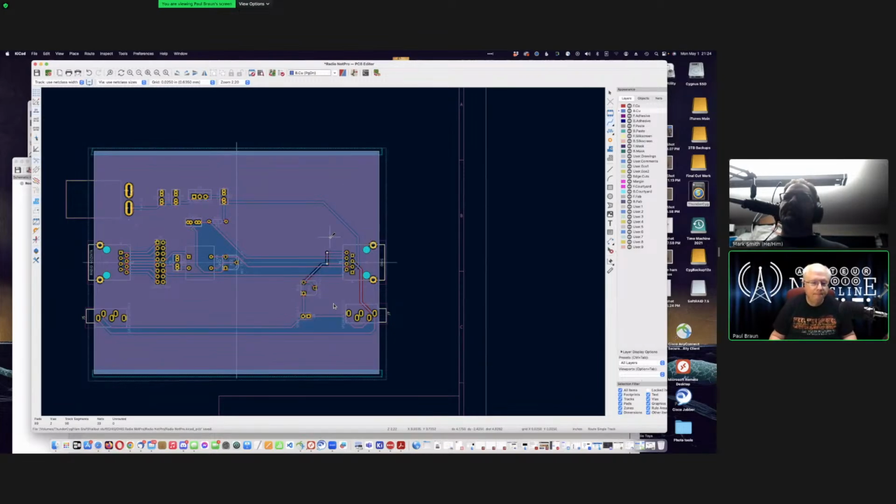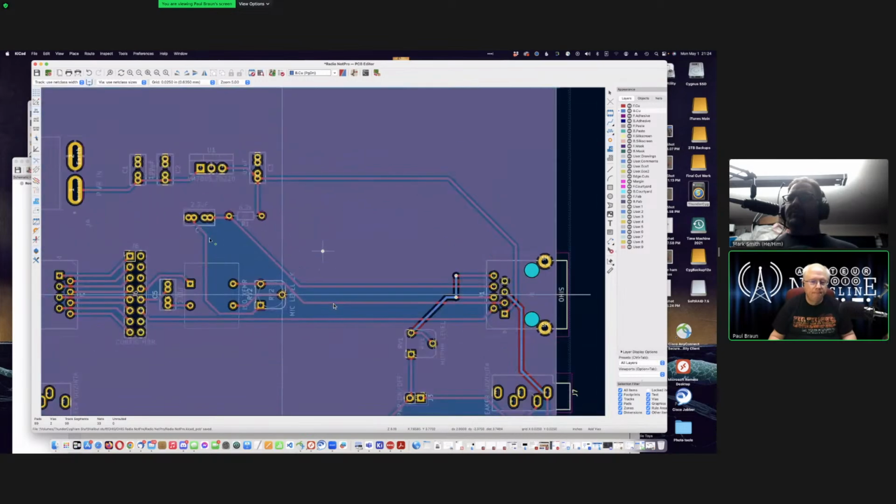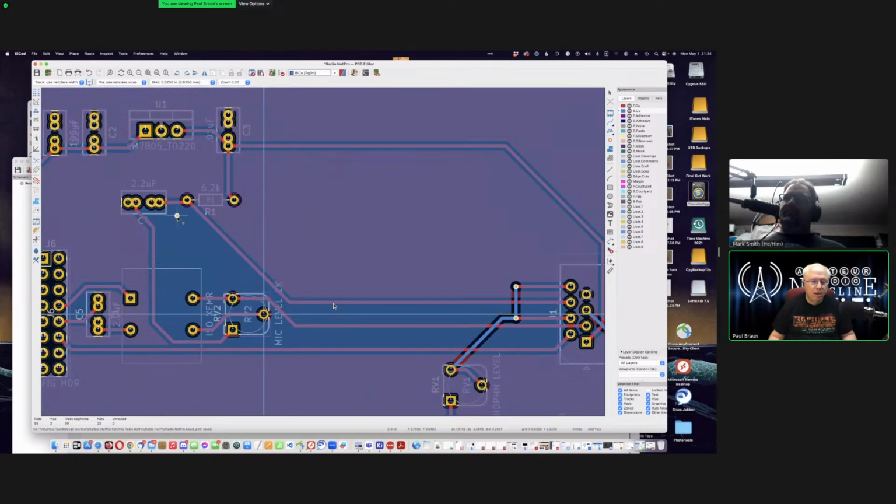Okay, so we've got some islands in there. Go back to the via tool and click some vias in those blue areas, those islands. Oh, they're blue because we're on the bottom layer. But there's no red layer, which is the important part, right? Because we have isolated our copper pour.